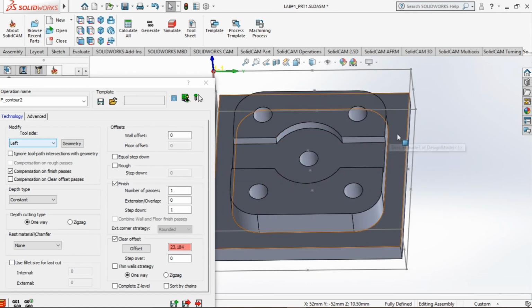boss area, right? So from that point to here, the total tool length would not be sufficient at the corner. So we'll have a small offsetting, like the first pass will be going closest to this boss area, right, and the second will be with a small offset, right? So anyways, that is called the step over. So the step over needs to be a value.